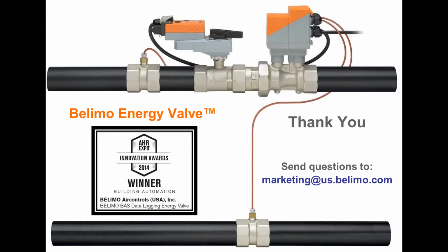So we've had clients ask about applying voltage to the input to drive the valve to its full flow position, and then using delta T management only to modulate the valve. But I don't think anybody's actually implemented that. As it is now, it's really advantageous to have it tied to your controller, because then you can modulate based on discharge air temperature, just as you would any other type of control valve.